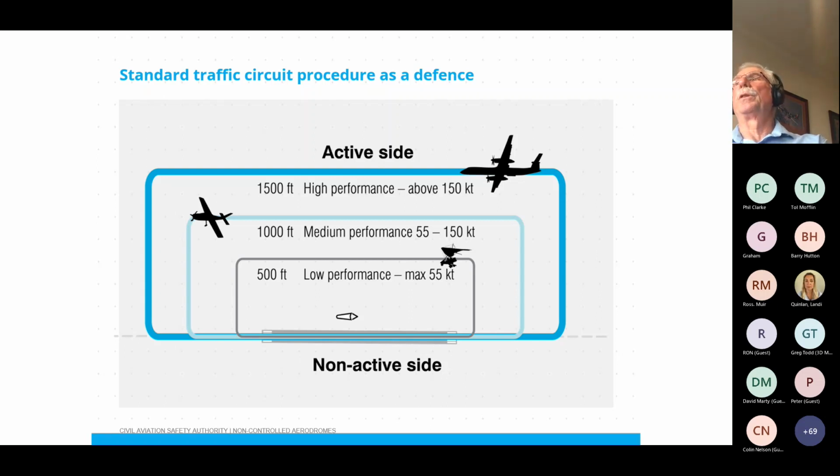You're right. There is a bit of an issue with that, and there's an increasing number of RPT aircraft going to uncontrolled aerodromes at the moment, and I don't think a lot of pilots appreciate the speed difference between their aircraft and their own. And they don't project how much space someone would need to fly a standard circuit. We talk about speed, but speed also equals how much space they need to make a standard circuit and still fly their normal profiles. So they'll quite often turn where they would normally turn onto base, not realising that there's an aircraft of a higher performance that's turned a wider base out of necessity, and then putting them into a conflict on base and final.